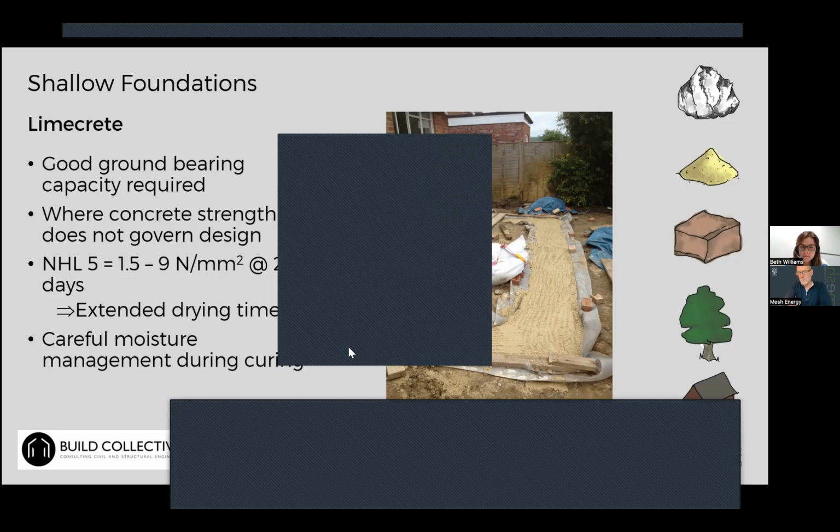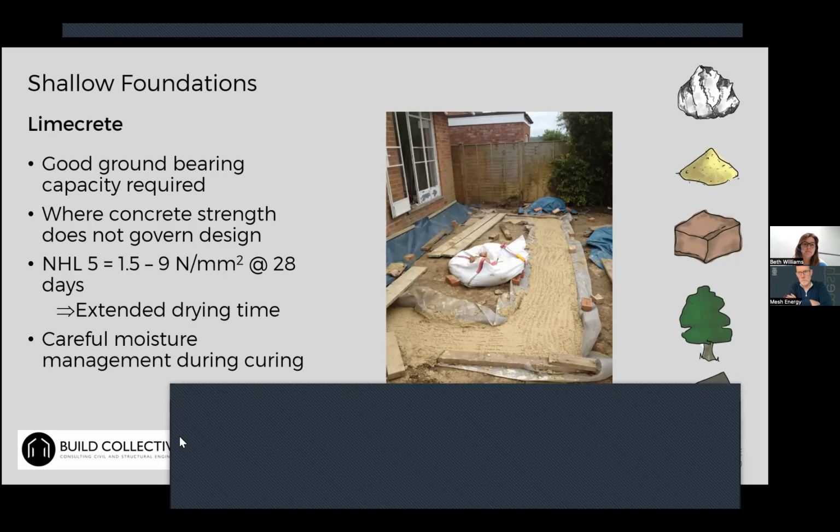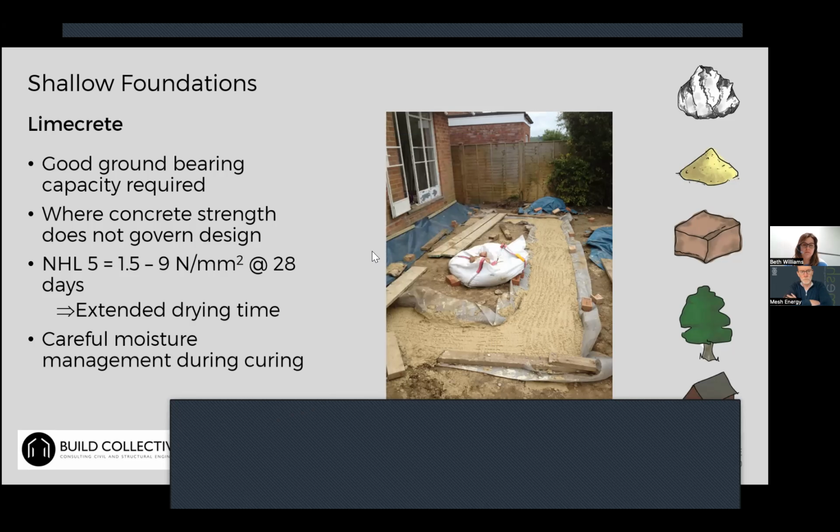So I understand the question was about the hardening of the limecrete. What's the issue? You need longer for it to gain strength? It's not necessarily that you need longer. Some of them just never achieve the same strength. With concrete, you get hardening curves which show you for each grade of concrete exactly what strength it's going to meet at different times during its curing. I can't remember how long they extend to, a few months, but 28 days is usually the critical one that we deal with.